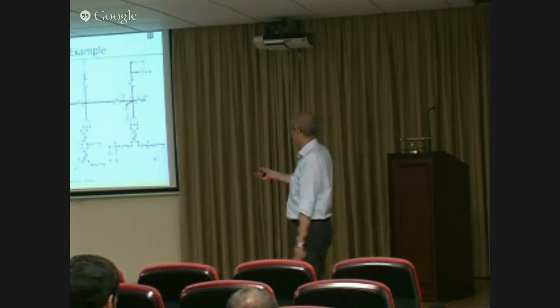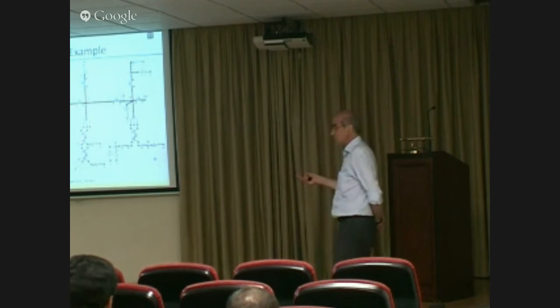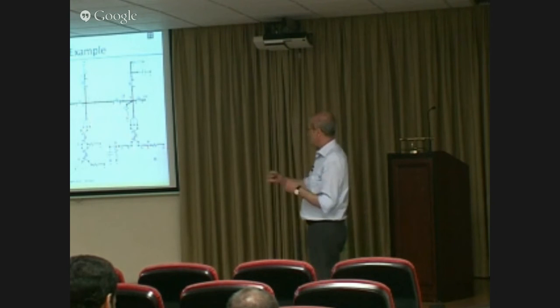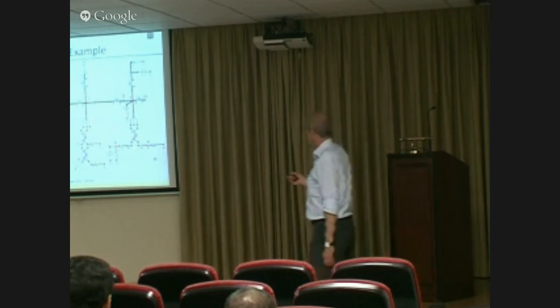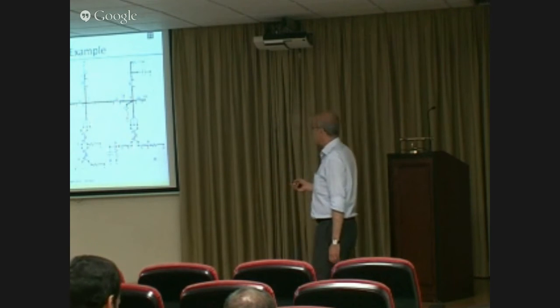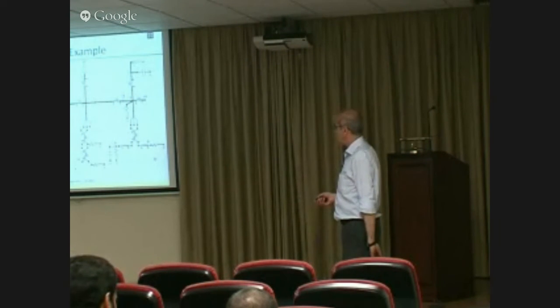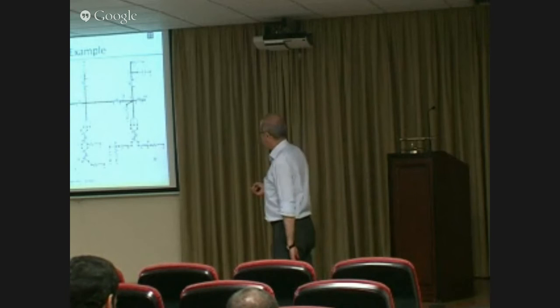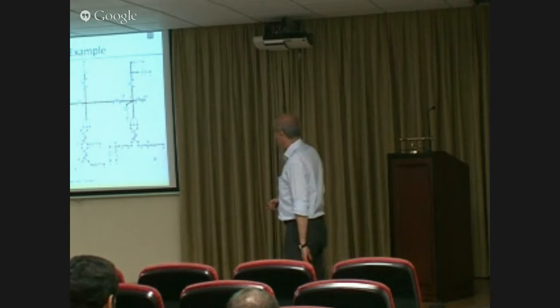The distribution system may start as a three-phase system, and then eventually it may become a two-phase feeder, and then finally a single-phase feeder. So you may see along the same feeder three-phase, two-phase, single-phase sections. This is an example where this is the case. As you can tell from the picture, this is an ATP model. It's a three-phase feeder, and then there are single-phase and two-phase feeders here.